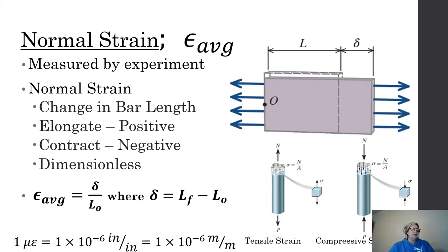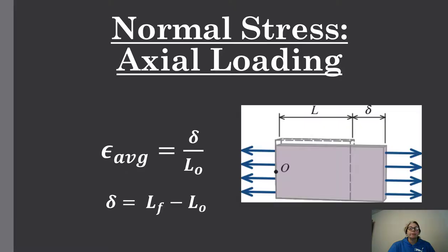Okay, so again, normal force, normal stress, tension, elongation. Normal force, normal stress, compression, shortening. And it's just that we're looking at that perpendicular force on an area and how it affects it. That's the strain, change in length over length. There you have it. That's our new formula.